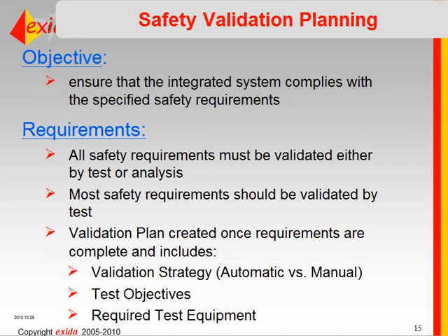All right, and then once the requirements are done, you can work on the safety validation planning. The validation will ensure that the system, the end system, the integrated system, complies with the safety requirements. And in this plan, you're going to define how you're going to do that validation. And so the requirement is that all safety requirements must be validated either by test or analysis, and most must be validated by test. So you're going to create tests to verify that most of the safety functions are working.